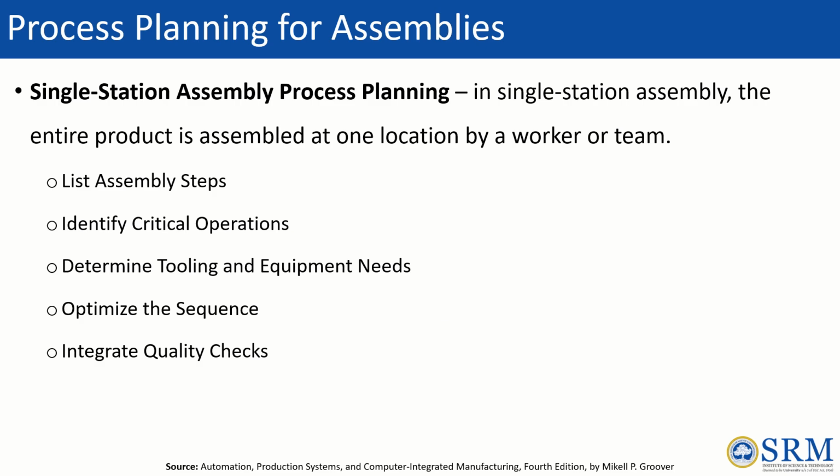Single station assembly planning is commonly used for low volume or customized products. The planner first lists all assembly steps, identifies critical operations, determines tooling requirements, optimizes the assembly sequence and integrates quality checks throughout the process.